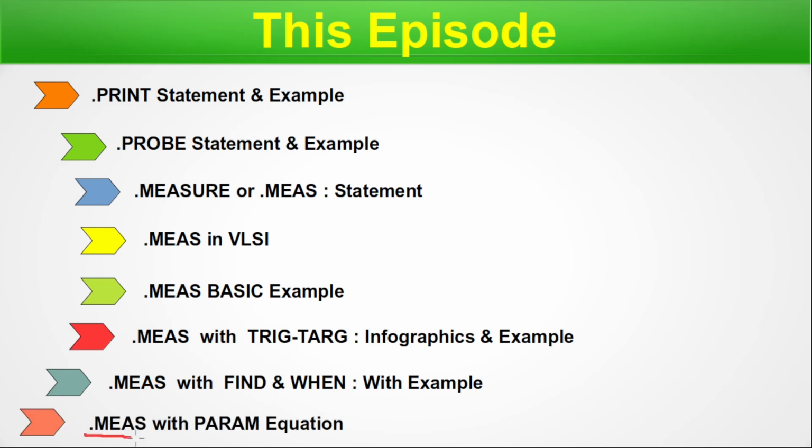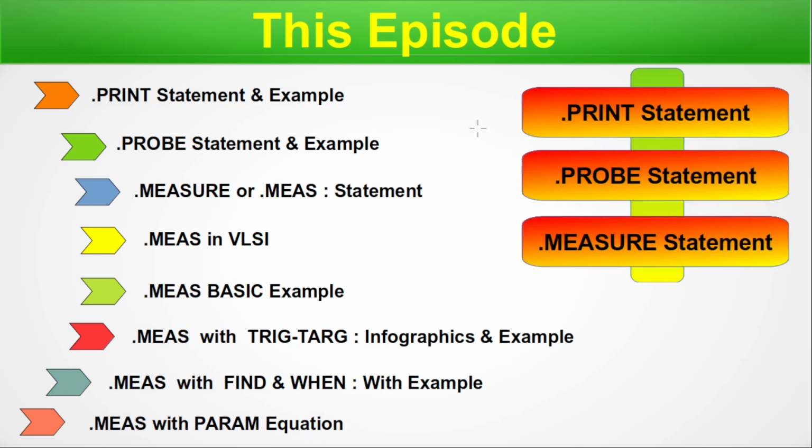Finally, we will talk about the dot measure, how the parameter that we have already learned can be clubbed with the dot measure to calculate complex equations. In a nutshell, in today's episode, we will talk about the print statement, the probe statement, and different flavors and usage of the dot measure statement. So this is the menu for today. Without any further delay, let's begin.